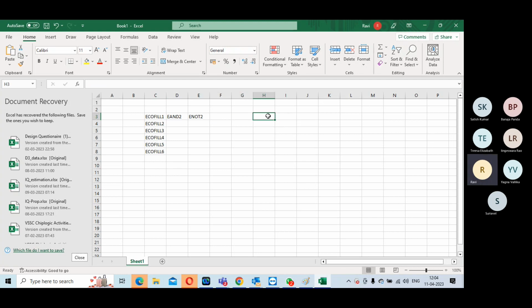Whichever is mapped to this, if you want a NOT gate, then you will get a 2x NOT gate which is mapped to this ECO fill 1. If you want a 1x NOT, it tells you which ECO cell you can swap. Similarly for NOR and whatever else is mapped. So this map table will be provided to you. No, the map file is different, but this particular stuff will come from the foundry. It's a separate thing.